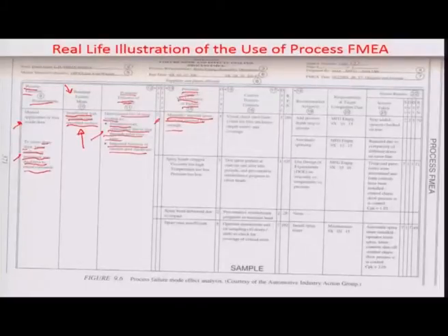because the manually inserted spray head may not have been inserted far enough because of an operator error. There can be another failure mode related to the clogged spray head. Sometimes, because of continuous spraying and insufficient maintenance, the wax may jeopardize the orifice of the dispenser, and it may create a lesser flow. A lesser flow matters because there is a certain time cycle which can be utilized for coating the wax on the door inner. You can't go beyond the time cycle, because in a line production, this cycle time has to be obeyed.